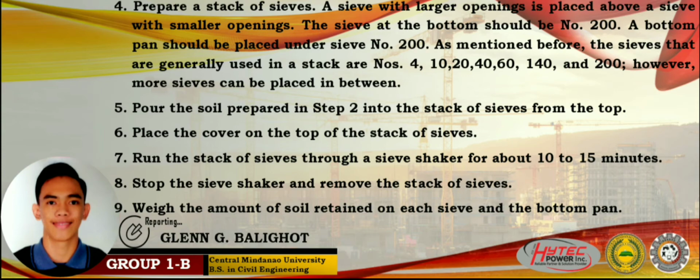Run the sieves through a sieve shaker, which was mentioned earlier, for about 10 to 15 minutes. Then stop the sieve shaker and remove the stack of sieves. Then lastly, weigh the amount of soil retained on every sieve prepared.